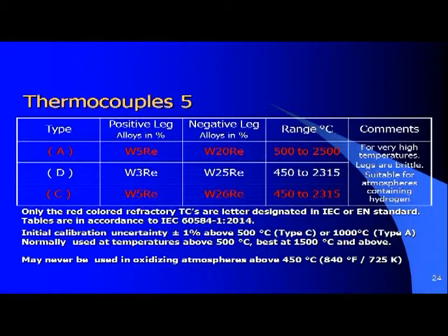But you must take into consideration that both thermocouples show a recrystallization effect above 1,250 degrees. So after the first 1 or 2 heating cycles, you may find that the permitted deviation is outside the 1%. We often found it. It is not because the manufacturer is unable to produce quality material. It is a metallurgical effect.